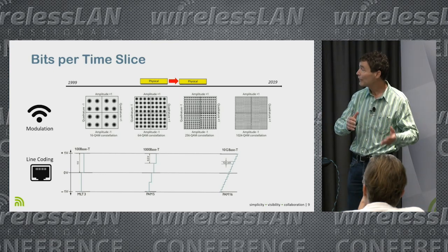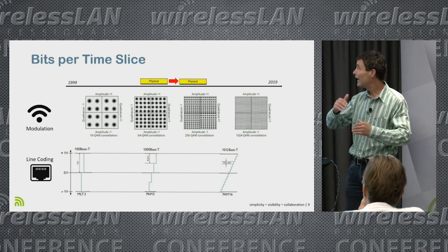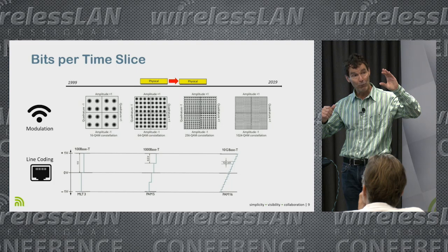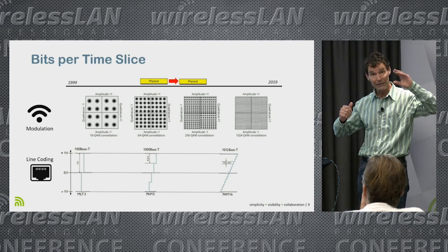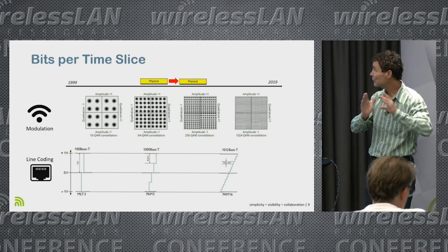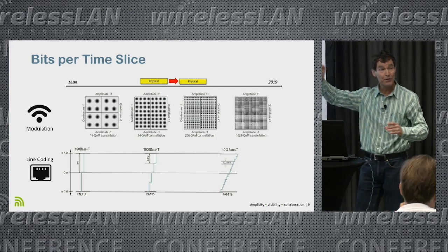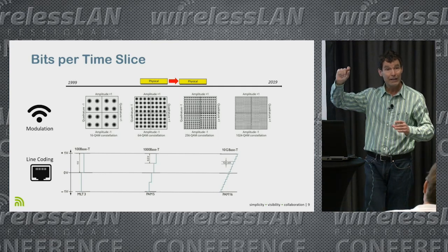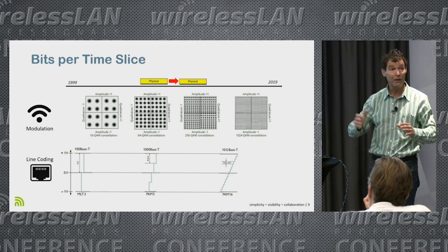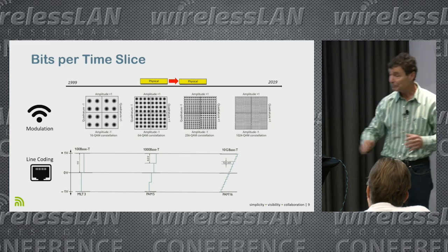Back in 100BASE-T, it was a very binary thing. You got a 1 or a 0, and then they started to get into breaking up this voltage swing on the wires into a couple of layers. Now they could cram a couple of bits into any time slice, and as we get to 10GBASE-T, you're down to these little 133 millivolt increments for each bit of resolution. A lot of this, just like in Wi-Fi, has fallen upon the digital signal processing to pull the signal from the noise.